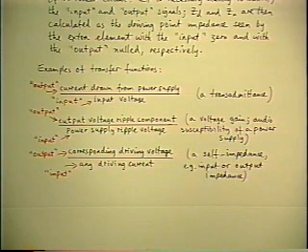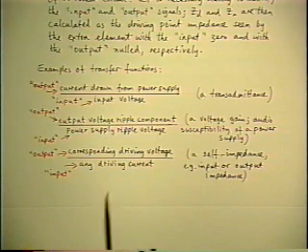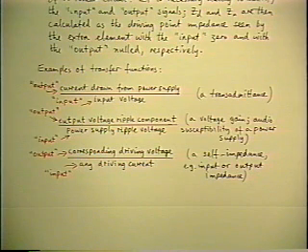That's another kind of transfer function. A second kind, listed under here, is that the power supply itself is not going to be perfect. It's going to have some rectified ripple on it, probably off the line, maybe 120 hertz or so, maybe a volt or two. And you have another specification on your amplifier that says that power supply ripple in the amplifier output has to be less than some specified value.